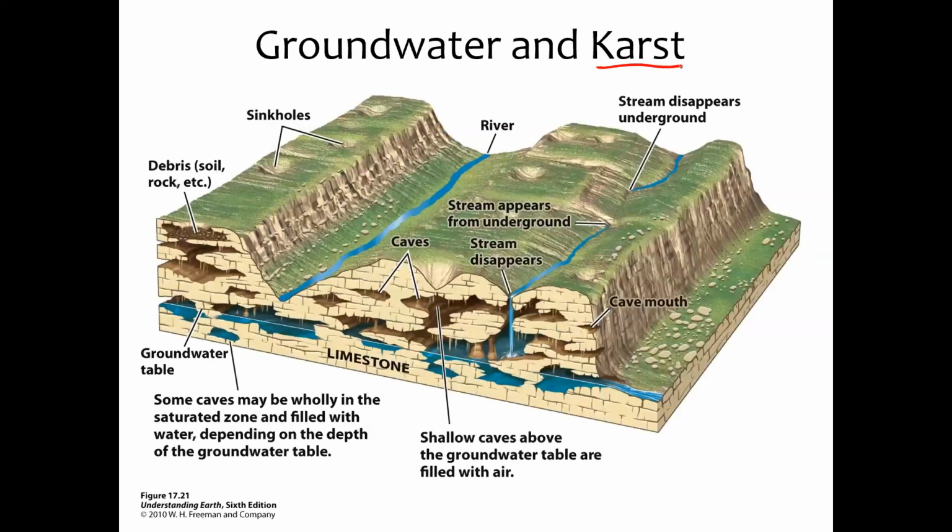So karst is related to the fact that some rocks dissolve easily, especially limestone. And so in eastern Tennessee, we've got a lot of limestone. We have karst because that limestone can dissolve fairly easily. Because that limestone can dissolve underground, you can generate a system of caves, some of which are partially filled with water or fully filled with water at depth or partially air filled. Regardless, if those caves are near Earth's surface, that means that there's not a lot of rock supporting the ground surface above them. And at times, they can collapse.